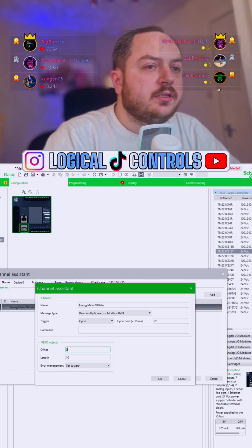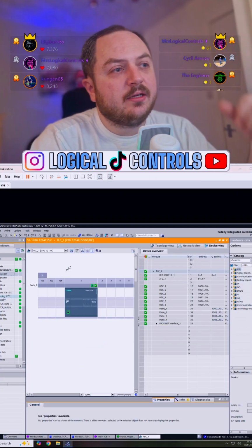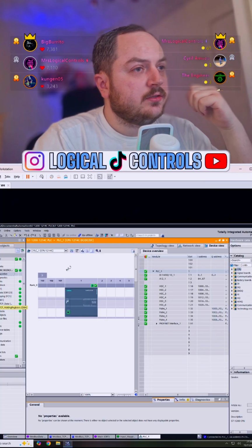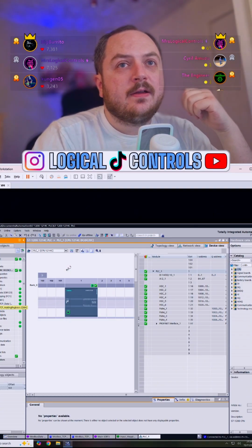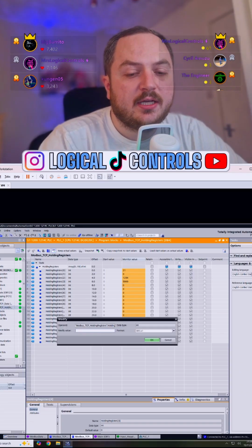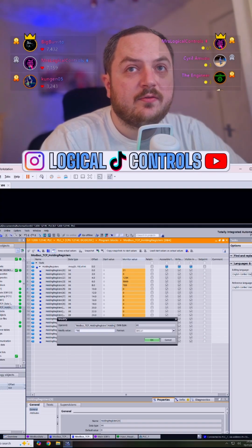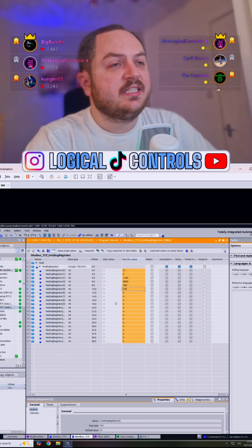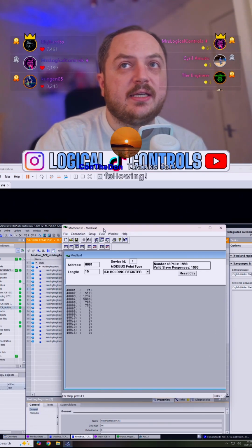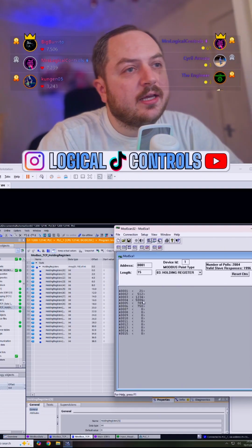So I can show you, if you missed it. I'm assuming a lot of other people missed it as well. I've got a Siemens PLC in my office at the moment. I've powered it up, so it's in a completely different room to me. If I look into this data block here, there's a number of values on here, so I can set 789. So I'm just writing directly to that PLC through the PLC software. This is information that is stored in the PLC at the moment. What I'm able to do from my PC, and this isn't through the Siemens software or anything, is read that data.